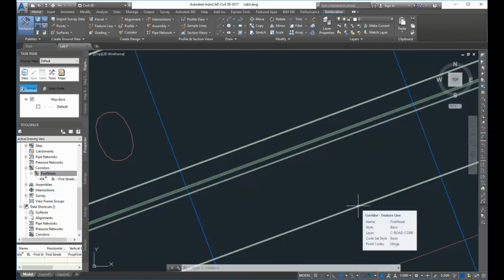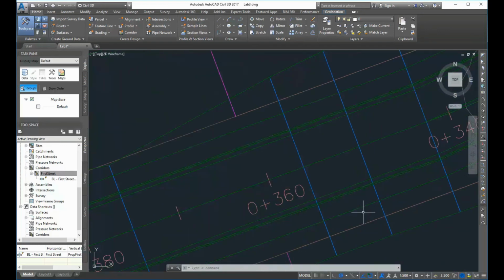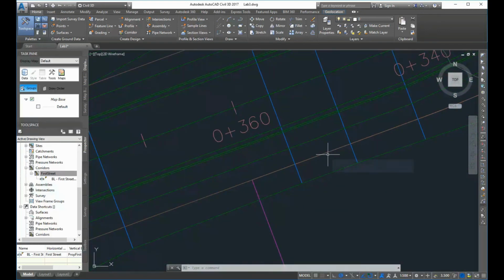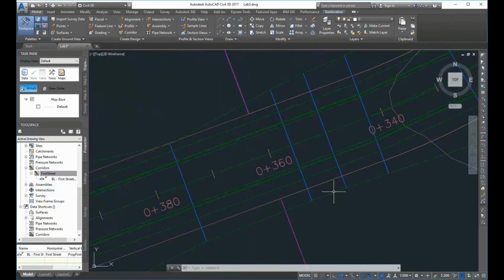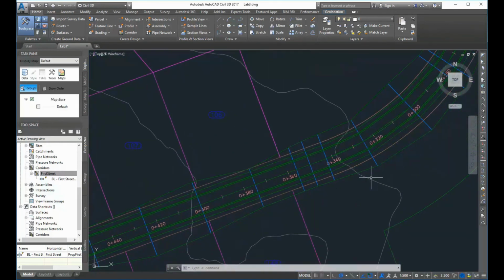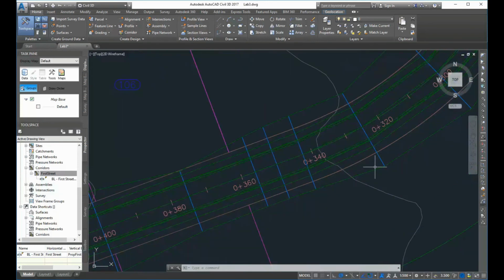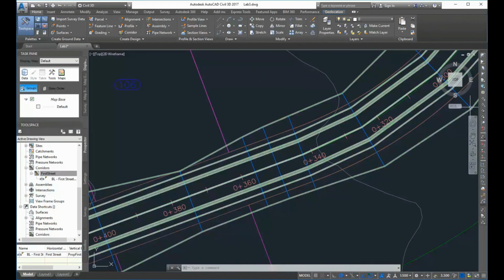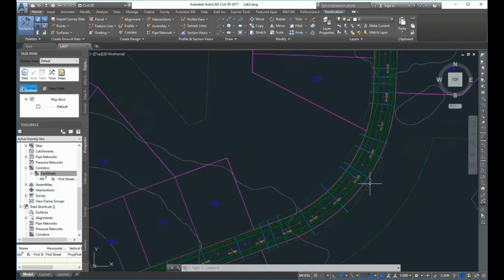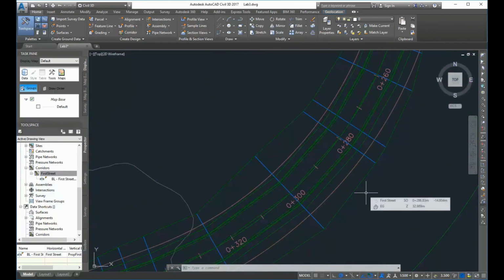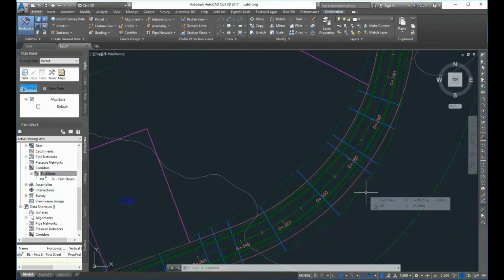This is a hinge point, which is also known as the back of my sidewalk. And then I can start to see how it's doing cutting and filling. And so the ends, these lines that are coming out here, this is where it's matching with the existing ground. It's finding that it's intersecting with the topography of the road.